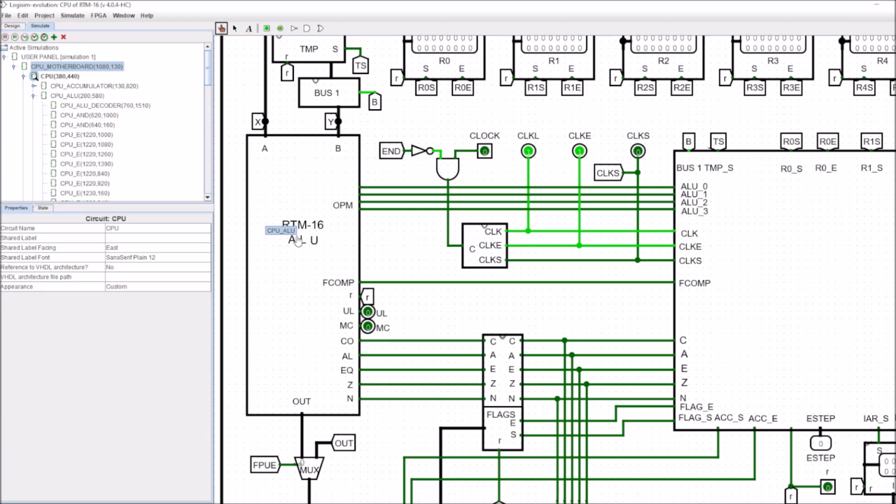So if the ALU is no longer in use, the control lines here, which were coming out to pick the functions within the ALU, are now free to be used to choose the functions in the floating point unit instead. So these control lines become available to us whenever the ALU is no longer in use.